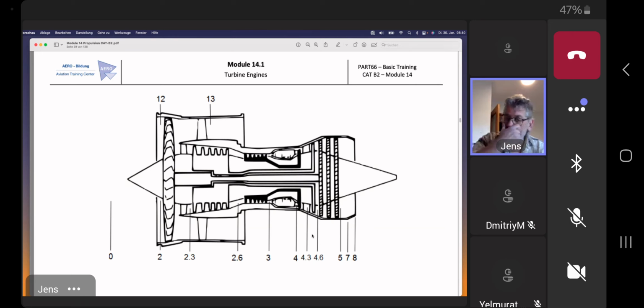Talking about EGT, exhaust gas temperature, normally, to be fair, we should measure the turbine inlet temperature, the TIT. But since it was difficult from the technology and materials side, the manufacturers started very early not to measure the TIT, and therefore they place the probes somewhere here.